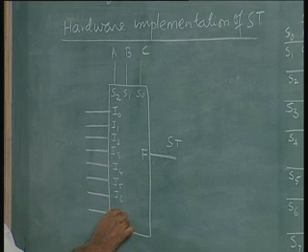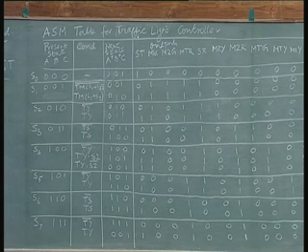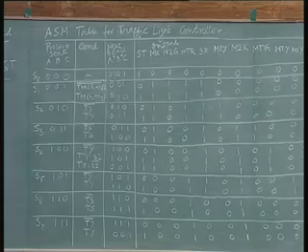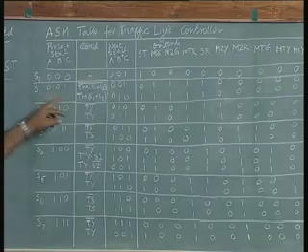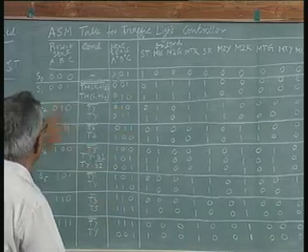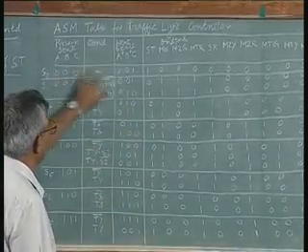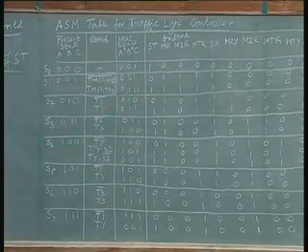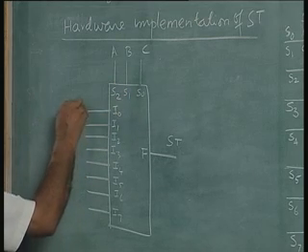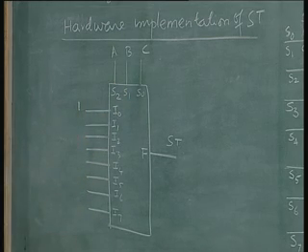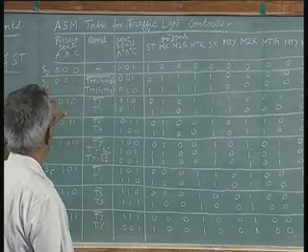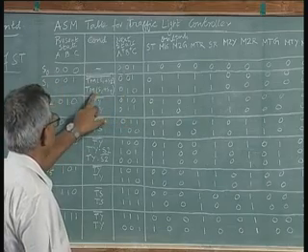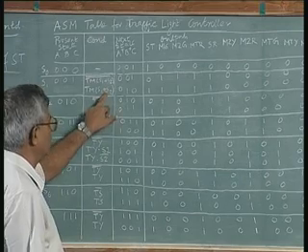What are the conditions under which the start signal is 1? That is all we have to map in this multiplexer. In this multiplexer we put the inputs by looking at the conditions under which start is 1. Start is 1 for the present state 0 0 0. So if we are in present state 0 0 0, start is a 1. Start is a 1 in S1 provided the condition Tm (S1 or S2) is valid.